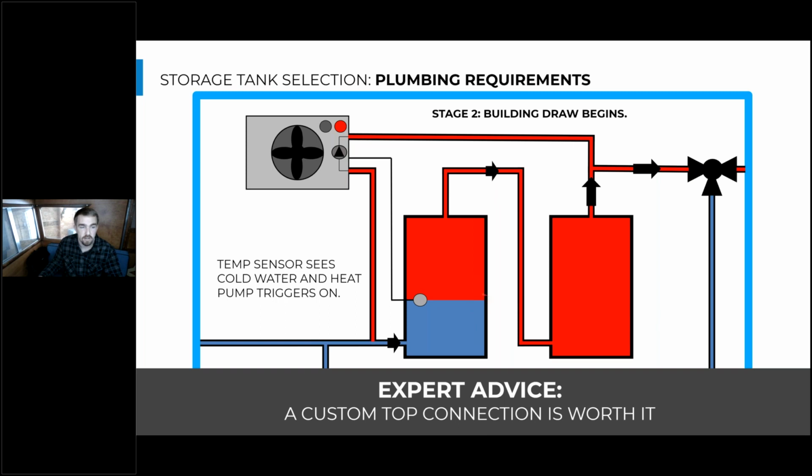So as soon as this stratification layer passes this sensor, the heat pump sees a quick drop in temperature and says, I need to turn on and recharge these tanks.